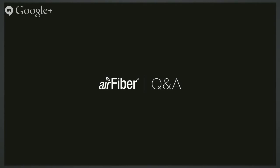Wow. Well, yeah, I can. I think it's written down. I'm actually not the RF guy, so if I'm about to give you a procedure and it is wrong, I will post that I was wrong on the forum after I talk to one of the radio guys. But basically what you want to do is align the receivers. You end up with the two units initially mounted in a generic close-to direction, and then on one unit you want to scan it. You want to go up and down, left and right, kind of pointing it into an imaginary grid in front of you. And what you're looking for is the strongest received signal.